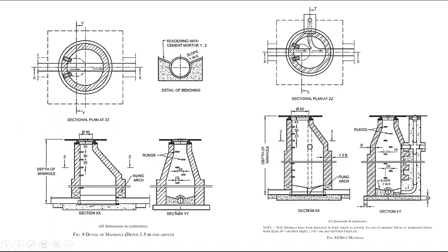And these are the civil details. You should not give these details. Civil people will do all the exercise. Your work is to give the depth of the manhole and the size of the manhole. That's all. The manhole cover and everything will come into the civil part only. Approximately, you have to keep the manhole wall thickness 200 mm for spacing purpose.